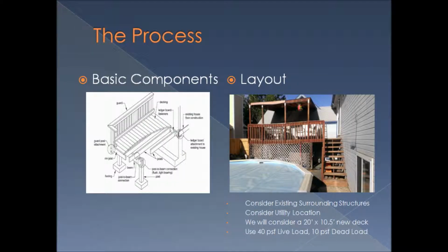Before we begin, I think it is best that I give you an introduction into the basic components of a typical deck. Starting with the base of the structure are the footings. These are concrete members that extend into the ground to assure the loads are being transferred from the deck to the foundation. Making our way up, we have the posts. These are attached to the footings and are the main load-bearing wood components of the structure.